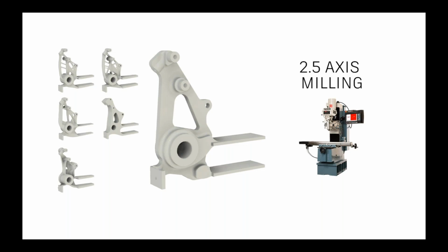What is the design output file type? When you are done with your generative solution, if there is an outcome that you want to keep, you can promote that back into Fusion as an F3D. So you would have it as a full BREP that you could then export as any CAD type that Fusion supports, whether it's an IGES or SAT, things like that. Otherwise you can also export the outcome as a mesh file, like an STL, if you wanted to take that downstream into other additive workflows that require specifically an STL.